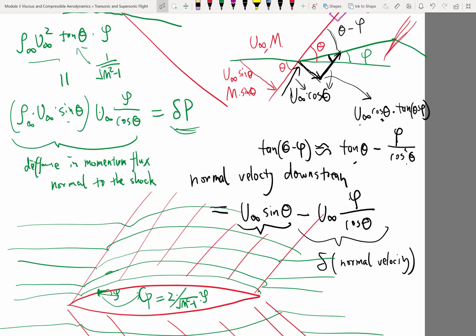Okay, and what's more interesting is the magnitude of the drag. The magnitude of the drag relates to 2 things. One is, what is the delta P? The delta P is proportional, for the same chord, to the angle, which is proportional to the thickness, right? It is also proportional to how much, basically, you have higher pressure, but the pressure works in this direction.